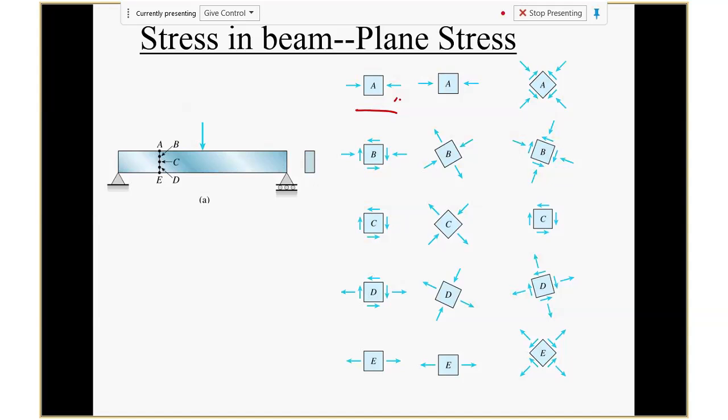That's plane stress. There's nothing in this direction, right? Then in the middle, you're going to have shear and normal stress. But still, nothing in the z direction, so it's a plane stress condition. In the very middle, shear is maximum, and normal bending stress is 0. That's what will look like this one. And nothing in the z direction, so it's plane stress.